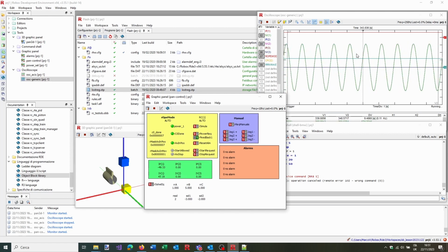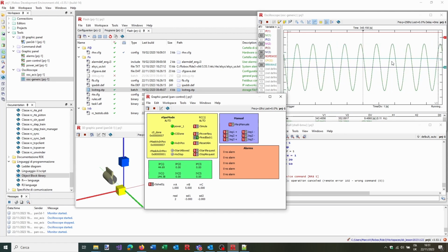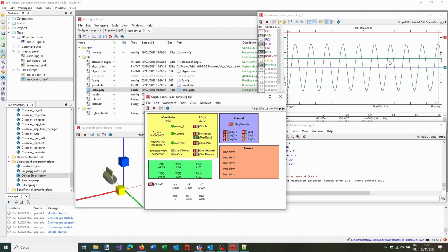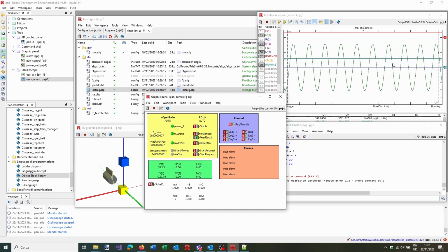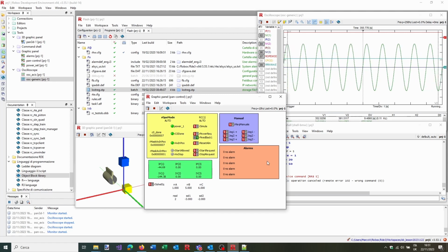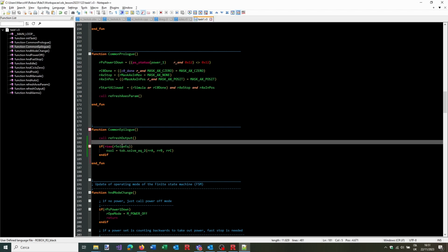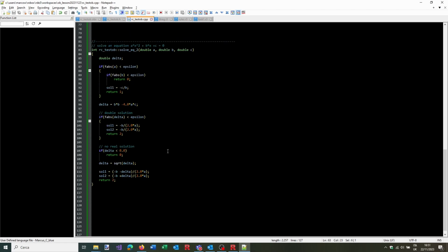Anyway, we never had any stop in the operation. That's because the rule and the task execute in different times due to the scheduler. So, while the rule is calling every time the motion, the task, just when it has time, it will come here, see the rise of the request, and just ask the OB to make this quick mathematics calculation.